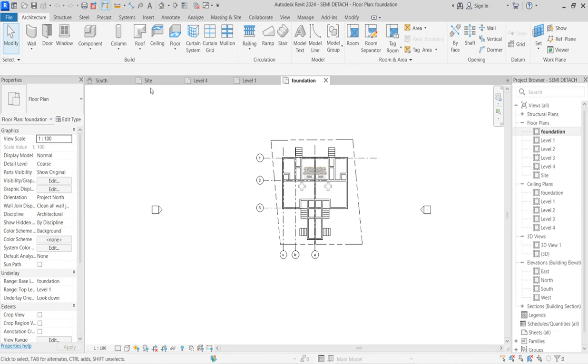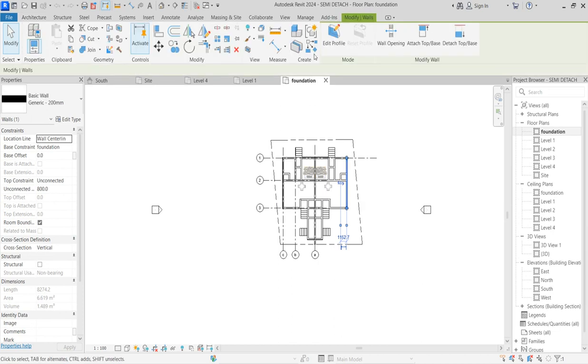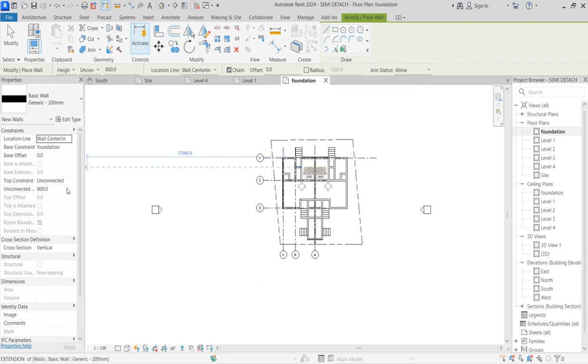And how do we do it? There is no big deal. We are going to use component to build, at the same time we work with the walls. So we are creating walls similar to this, and say create similar. And this part we are going to change the height to something like 2500 millimeter.